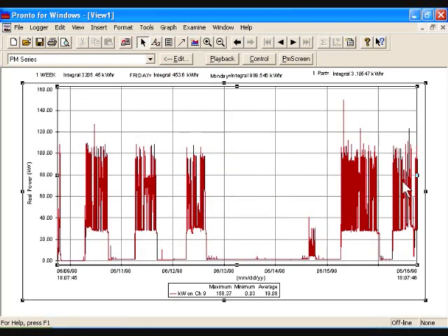So here is the kilowatt demand during the 1 week of this assembly line. 1 week's kilowatt hour usage was 3,205. One day, Friday, a light day, was 453. A heavy day, Monday, was 989 kilowatt hours. And to make just one part was 3 kilowatt hours, basically 3.1 kilowatt hours. This is extremely powerful. Now, if you wanted to, you could just click over on your printer icon here and print this.